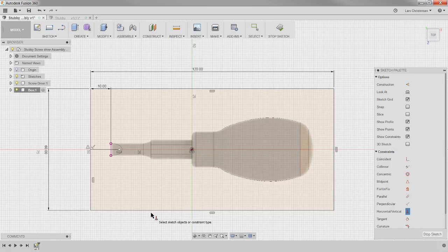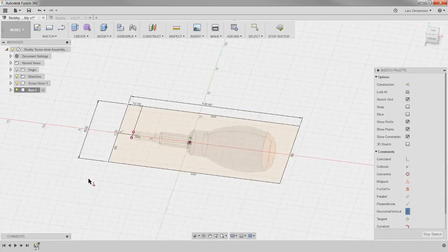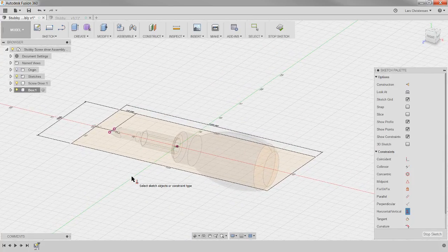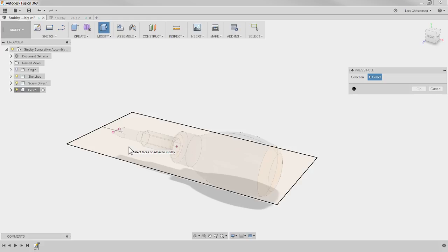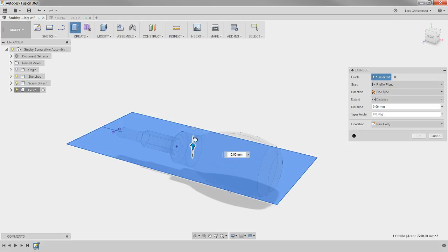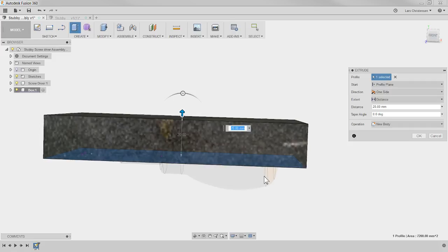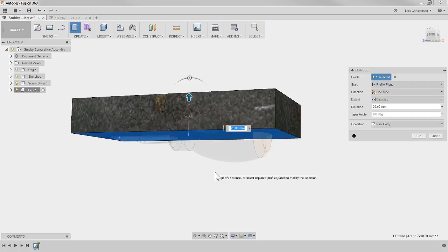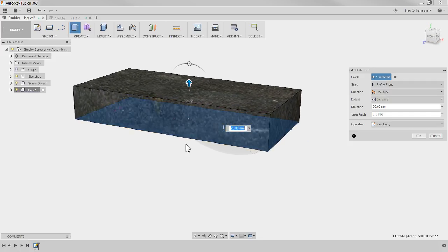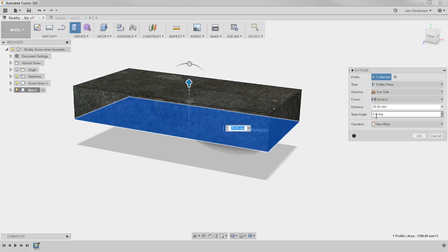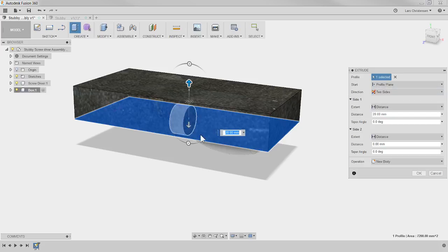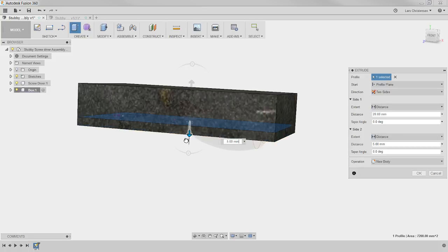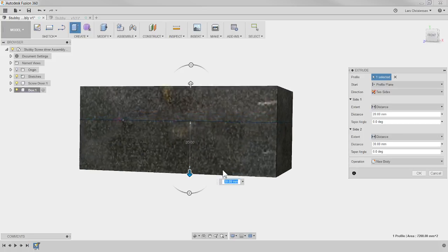Now, like I said, I'm going to use what I would call the Jimmy DiResta technique right now with this box. I'm going to hit Q, and I'm going to extrude this box up. So I'm going to go up kind of like with a lid, and the appearance comes with, actually stays within, the step files. So that's why you'll see the appearance is not standard steel. It's kind of cool. So I'm going 20 in one way, but I'm going to make it a little bit deeper the other way. So I'm actually going to go over in the extrude over here and say two different sides from that point. So I'm going 20 millimeters up, but I'm actually going to go maybe 30 down.